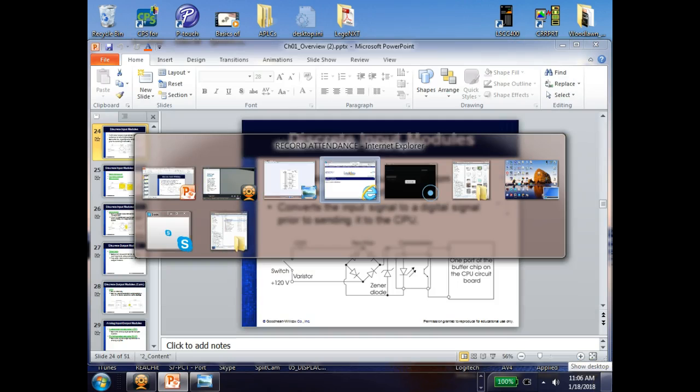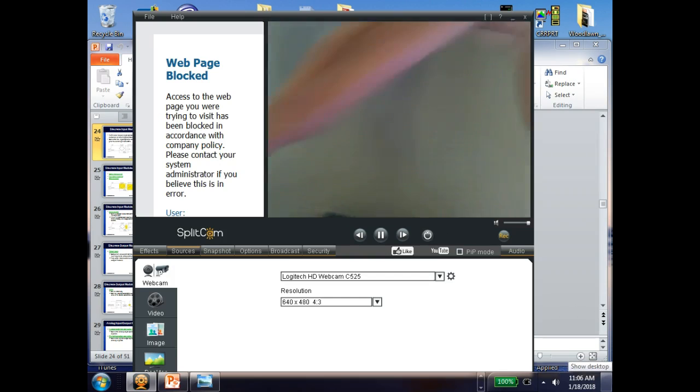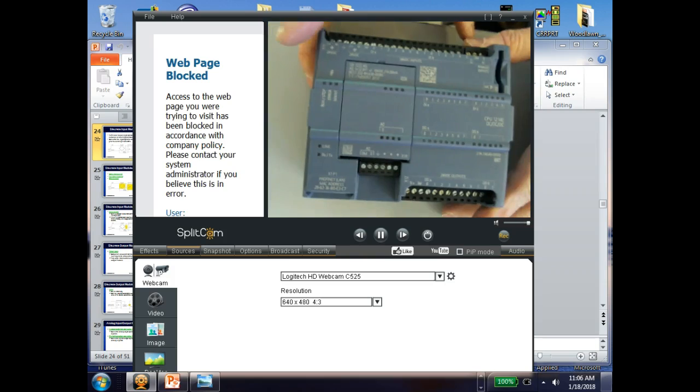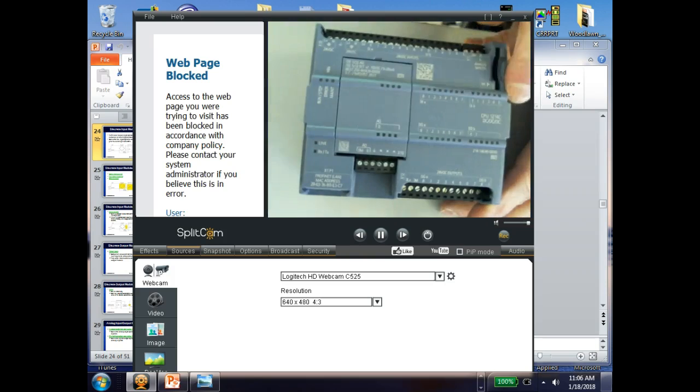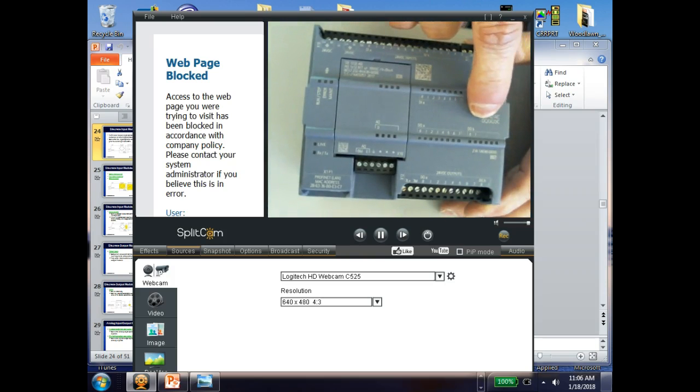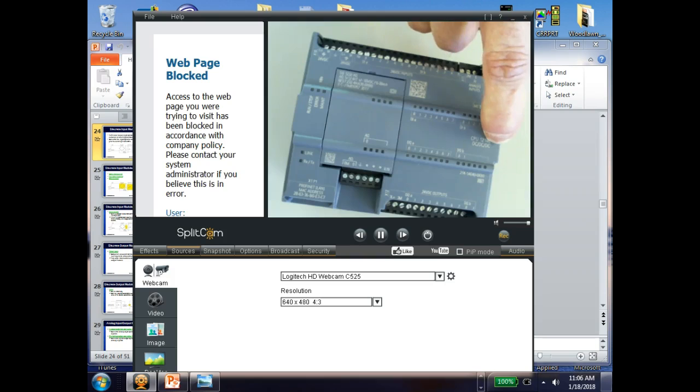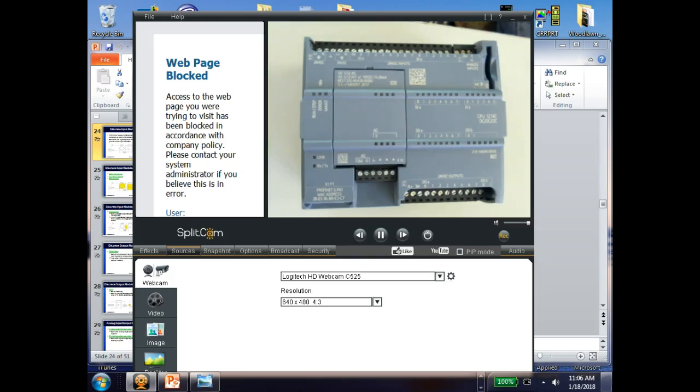So when I looked at the PLC, the three things they specify are: what do you need to power up the PLC on? Where's that, over here? Oh, right here. This says DC, DC, DC. So that means we power it on DC, my inputs use DC, and the last one is your output. If I looked at the Allen Bradley, it says AC, DC, relay. So that's the three things, and we'll look at that in a minute. So this Allen Bradley that I've got connected up here.